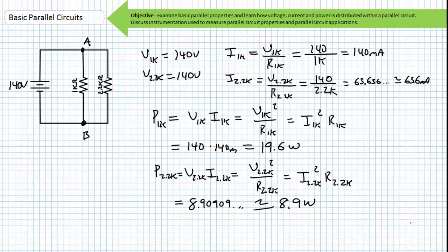For those with an interest in efficient and timely calculations, notice at no time did solving for voltage across, current through, and power dissipated by individual components within this parallel network necessitate you solving for total resistance of this parallel combination, despite the fact that we did so in one of our earlier warm-up exercises. This combo, if you recall, exhibited a total resistance of 687.5 ohms.